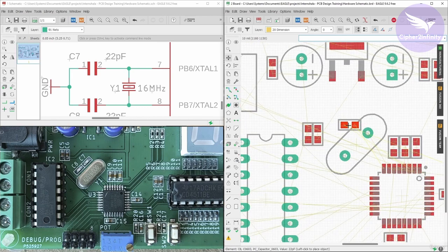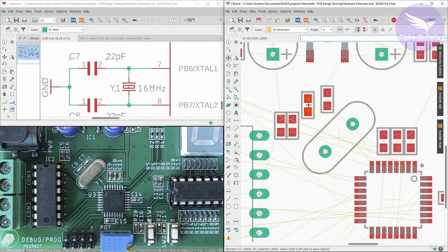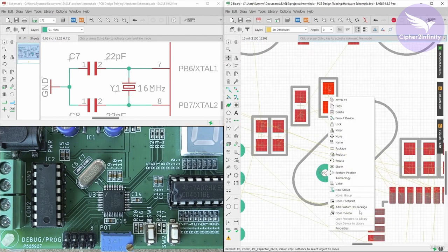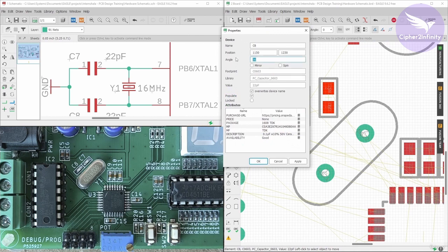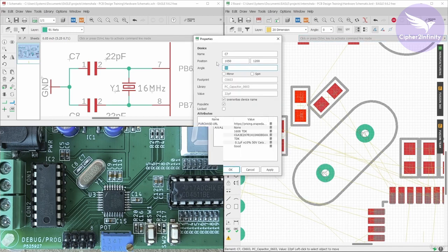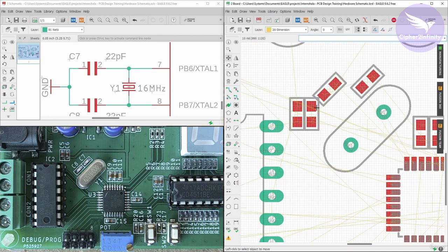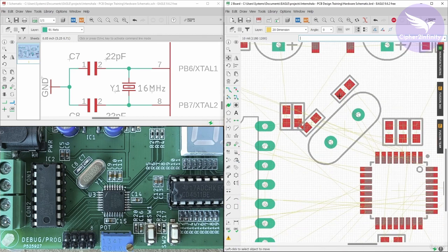and I'm going to place these capacitors near the crystal. And again let's place these capacitors with the angle of 45-degree. This is actually not mandatory, but just to make the layout a little bit nicer, I'm doing this. You always have to make sure that first of all your priority should be the component placement, and then the second priority should be the looks. Okay, so the first priority should be the component placement.